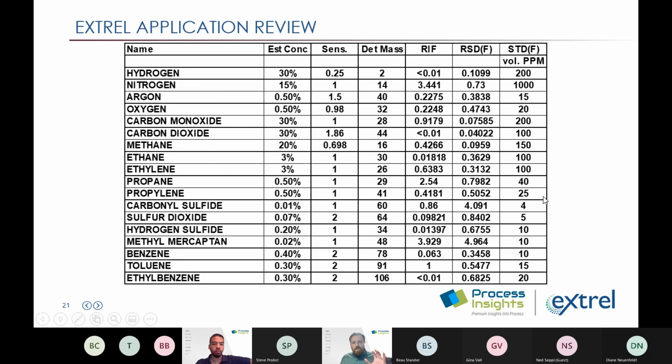We want to understand exactly what performance the mass spec is going to get on that flare prior to ever doing the installation. It helps the flare program be developed properly, knowing that they're going to be measuring everything they need and getting a good response. It also tells our engineers what calibration gases are going to be required in order to do that measurement.